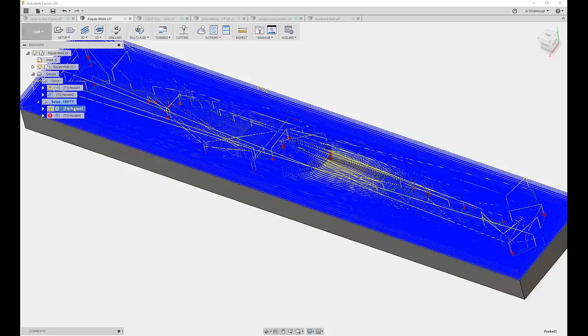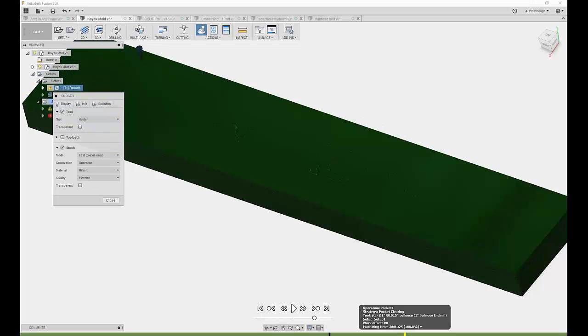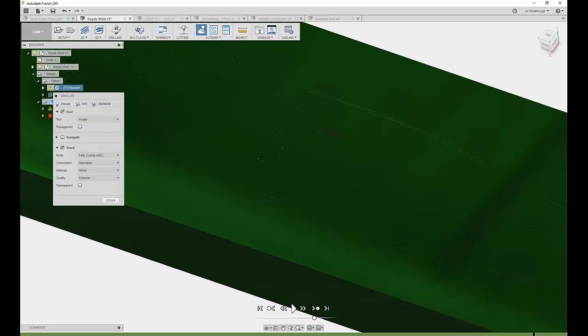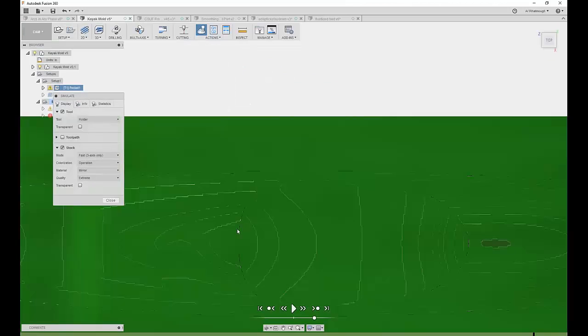So it's really up to you as a user to know when it makes sense to use one of the modes. The 3D fast mode, of course, is only for 3D toolpaths, where the standard mode is for indexed multi-axis toolpaths. So you are limited in what you do, but you sometimes get nice functionalities by using the 3D fast mode. If it's just 3D toolpaths, then that mode would capture a lot. It won't do collision checking, but that runs in Fusion in the background automatically, so you will still see if there are any collisions detected.